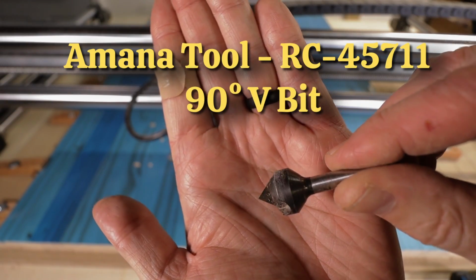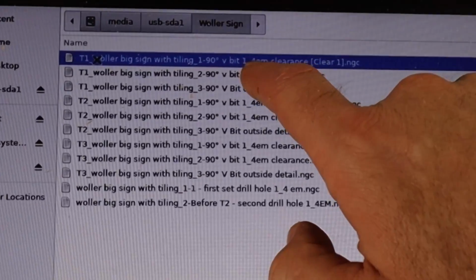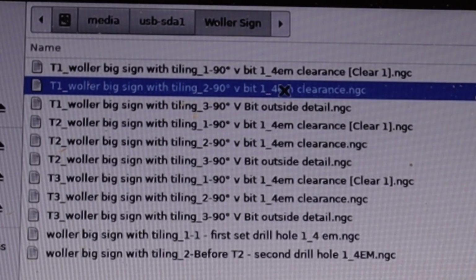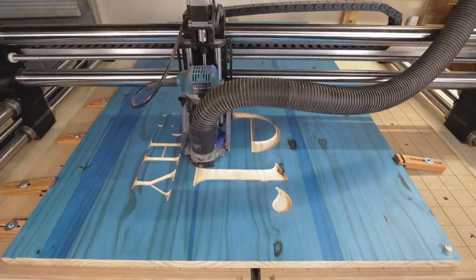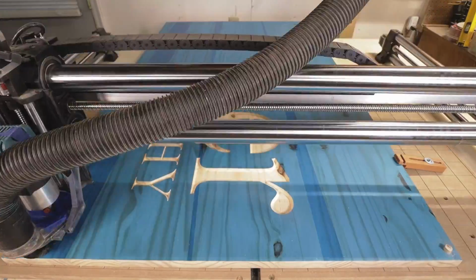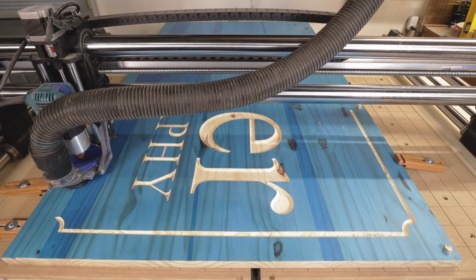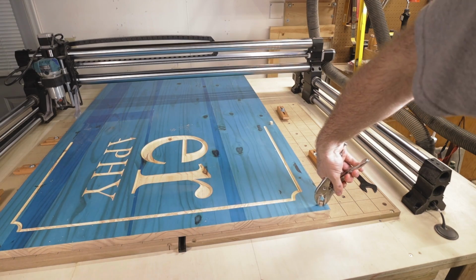And now we're going to switch over to the 90 degree V-bit and load the second tool path. And this is just going to do the edges and also the decorative line around the outside border. As you'll see later, you want to make sure your V-bit has nice sharp blades. After all the tool paths for tile 1 are finished, we're going to move on to tile 2.